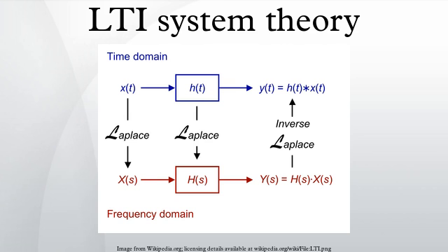Important system properties: the input-output characteristics of a discrete-time LTI system are completely described by its impulse response. Some of the most important properties of a system are causality and stability. Unlike CT systems, non-causal DT systems can be realized. It is trivial to make an acausal FIR system causal by adding delays. It is even possible to make acausal IIR systems. Non-stable systems can be built and can be useful in many circumstances. Even non-real systems can be built and are very useful in many contexts.